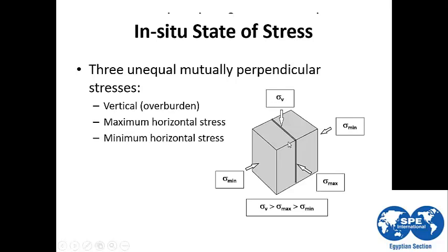You need to liberate this force by applying higher pressure than its minimum component. So the frac will propagate in a direction perpendicular to the minimum stress direction.